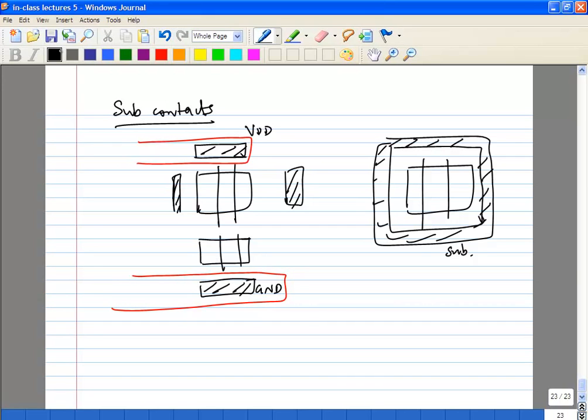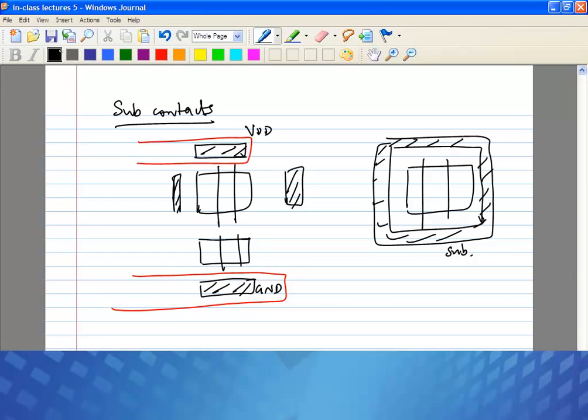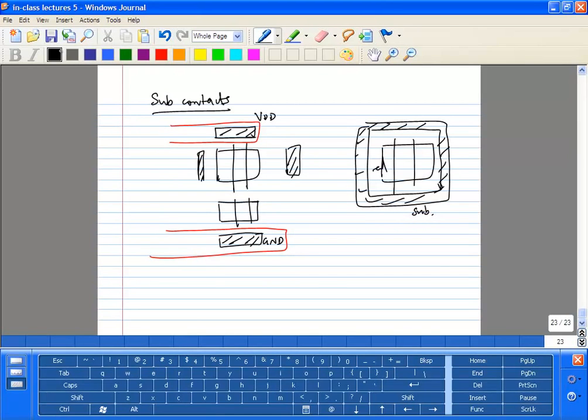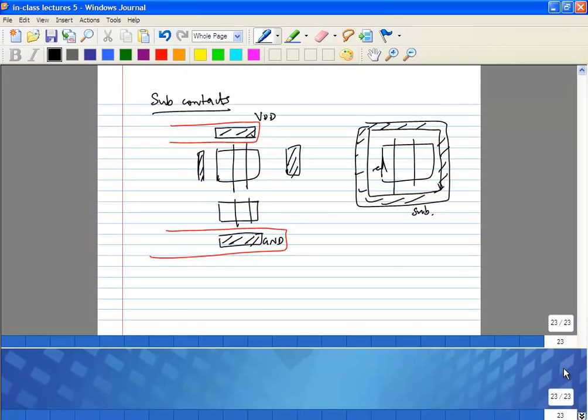That's one of the reasons why you give this substrate contact, because your substrate at the end is going to be connected to a central ground somewhere else, far away. So you want to give it a very short local ground, because otherwise this will be running on metal. The substrate contacts will be routed on metal.